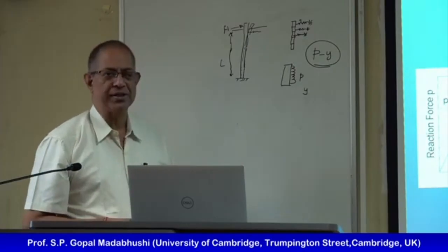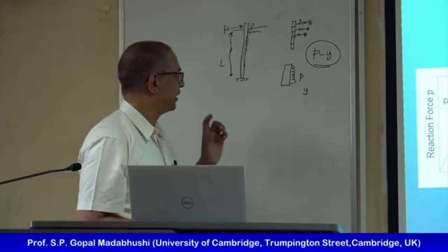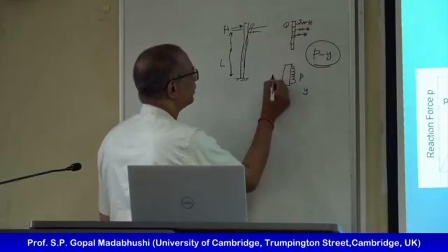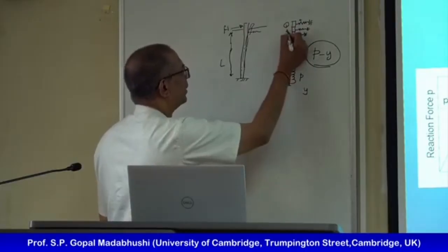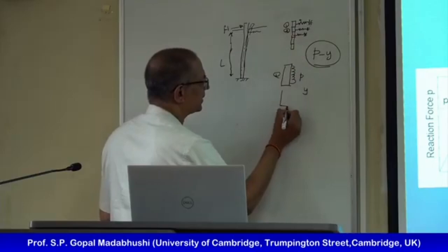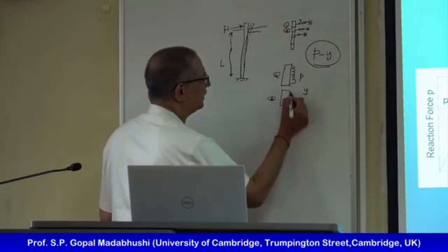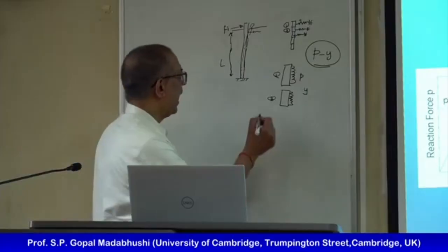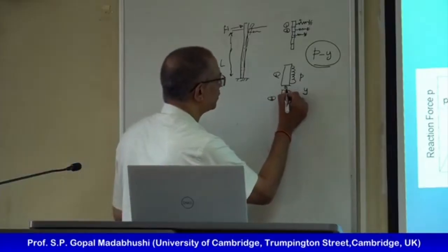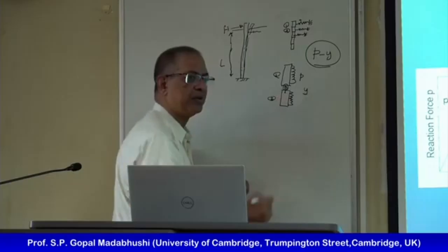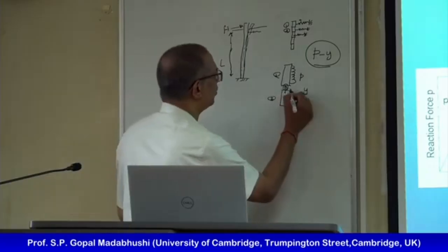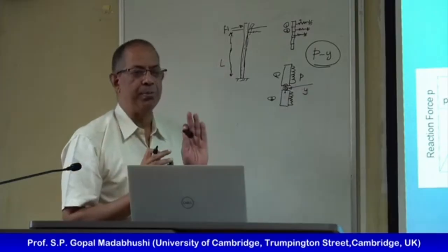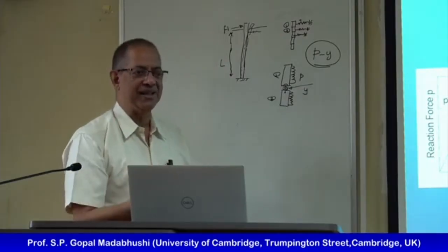Now, it's also very straightforward to imagine that, say, this is element 1, and this is element 2. So I can imagine that my element 2 is here. I got some more pressure distribution there. And there is a torsional spring between the two. So this is what you would call the structural spring, which mimics the bending stiffness of the pile.